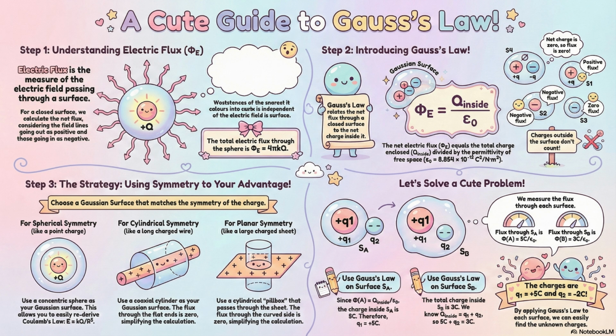It is. So we've traveled from the elegant, universal symmetry of Gauss's law all the way to volatile tantalum chips, silently degrading electrolytics, and ceramic chips that might lose 90% of their performance the moment you plug them in. And the bridge connecting those two worlds is permittivity. I mean, understanding how materials interact with and contain that electric field. That's the key to navigating all these contradictory specifications and failure modes. The knowledge that saves you from a pyrotechnic failure or a silent performance drop, it's not in the circuit theory textbook. It's in connecting the physics of the field to the chemistry of the material.